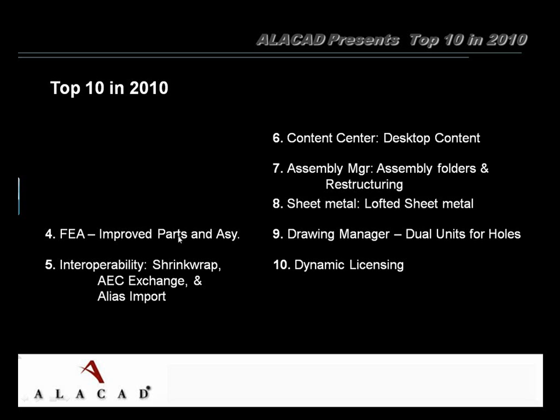I have much finer mesh control with finite element analysis. I also can do parametric design studies, so I can take a look at the material thickness and determine what's the proper material thickness to handle the loads I'm applying, and have it do that without having to run multiple iterations of analysis.